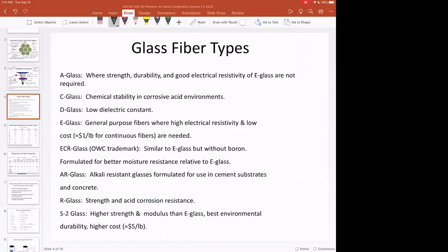If you look into the fiberglass or glass composite literature, you see lots of E-glass composites. Sometimes you see C-glass. There are a lot of different glasses though. R-glass, every once in a while. But if you want to make a fishing boat, you'll generally buy an E-glass composite, or an E-glass kit, or E-glass fibers, and those fibers will be sized for a vinyl ester resin or an epoxy resin, depending on what matrix you're going to use. This is just some nomenclature you should know if you go out and try to find different glass fibers. This is from the glass industry, and this is how they specify it.